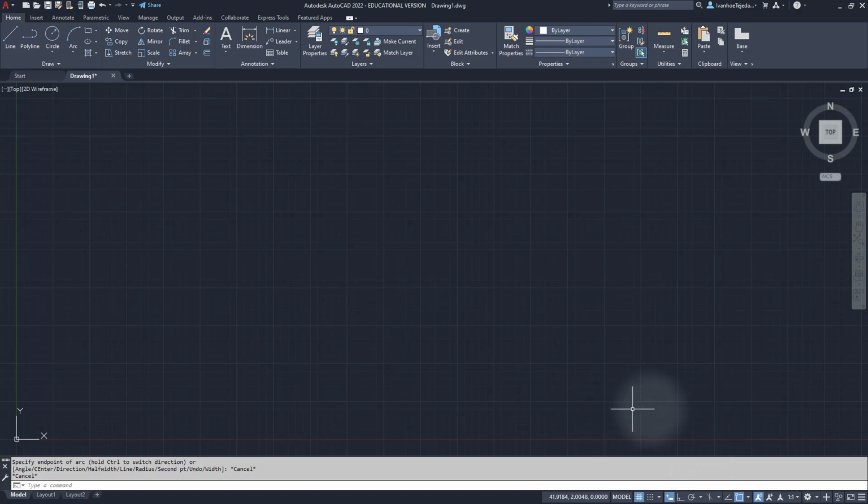The buttons commonly used are Dynamic Input, Ortho Mode, Polar Tracking, Object Snap Tracking, and Object Snap. Eventually, I will also be using the annotation scale. I hope this intro has been helpful. Once you start drawing and using the interface, you'll see how all these icons, tools, and drawing aids are used to construct architectural drawings of any size.